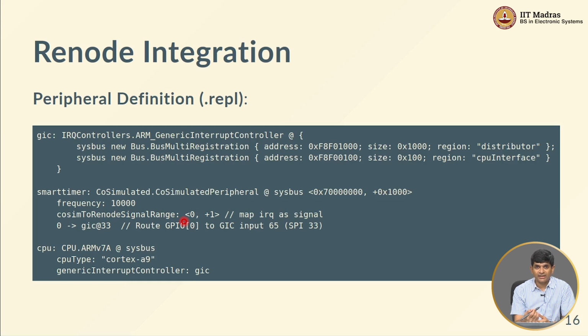The other things like the S_AXI and so on are part of the AXI bus and therefore Renode can actually recognize and automatically infer everything that is required for that bus. Over here the IRQ out, I need to specifically give some way by which Renode can recognize it as a signal which should then be connected to some other place. So I have this extra line over here just to indicate that there is one extra signal that needs to get mapped as part of the IRQ.